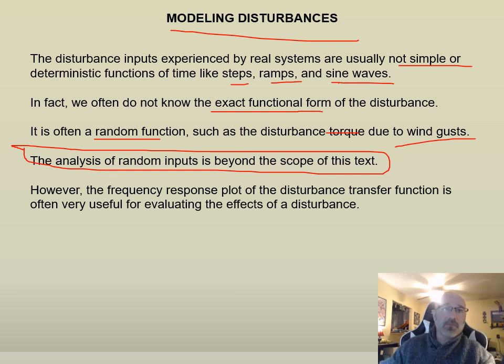One way in which we compare these is a frequency response plot. With these response plots, we can look at the signal with and without the interference, with and without disturbance, and try to extract it, do some transforms, Hilbert transform, things like that, to back out what that disturbance is so we can remove it from our system and do that background subtraction. So we might call the disturbance our background in our real life application that we need to remove from our system in order to analyze it properly.